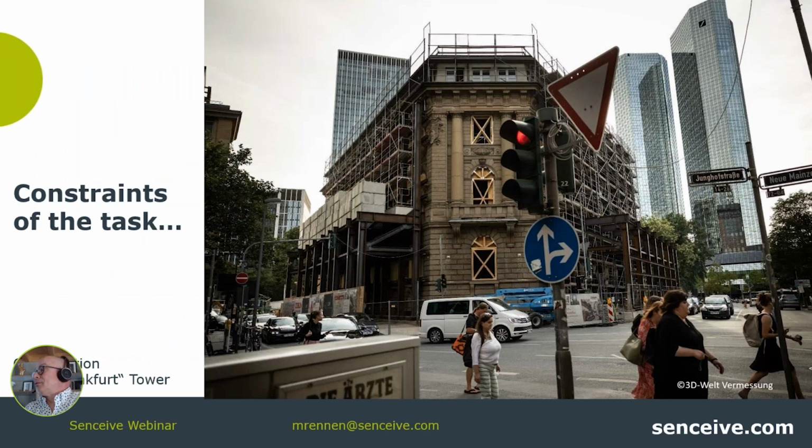This is an example from Frankfurt, actually the banking quarter of Frankfurt. In the background, you see the Deutsche Bank tower here. And this is a heritage facade that will remain. The core will be entirely removed, and the whole facade is just hanging on this scaffolding here. Then there will be excavation about 5 stories deep, and a 270-meter glass tower will be erected within this facade.